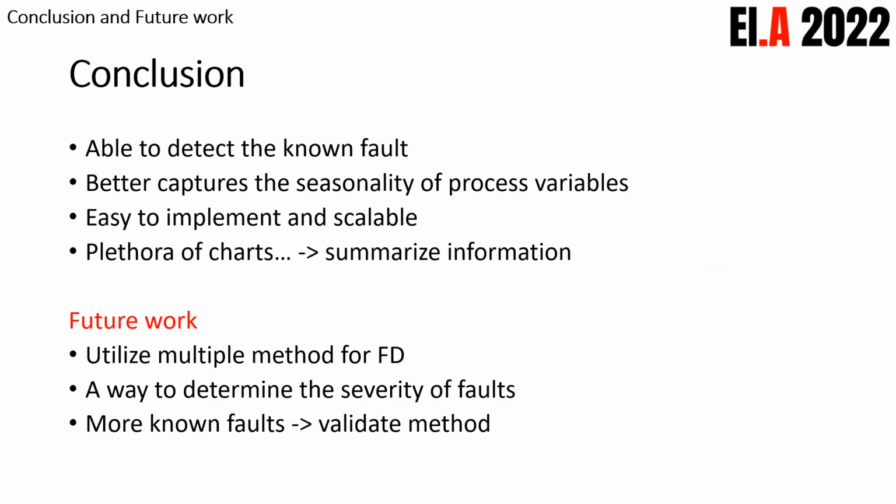To conclude, the method developed was able to detect the known faults with some thought behind the control limits. The method is better at capturing the seasonality of process variables compared to normal Shewhart charts, and it's easy to implement and very scalable. One problem is that it creates a plethora of charts, so there needs to be a way to summarize the faults detected for the different charts.